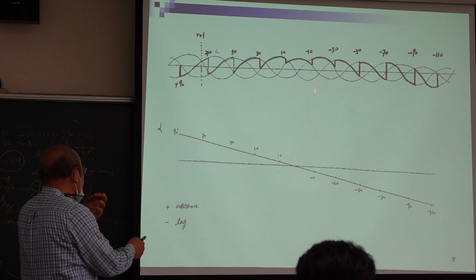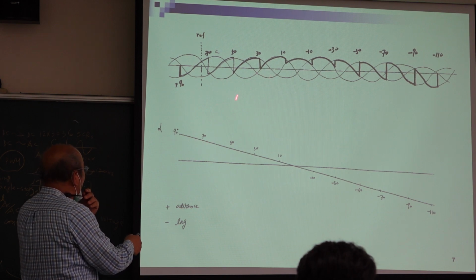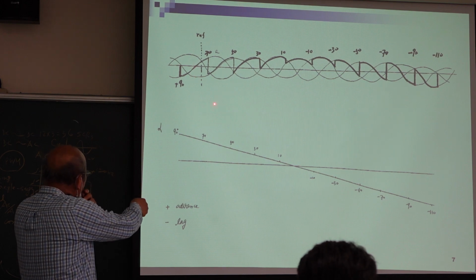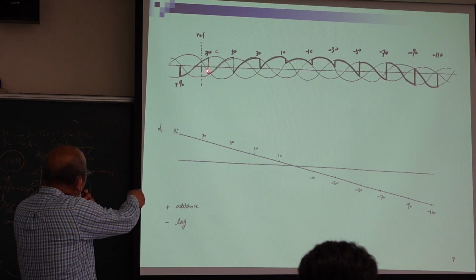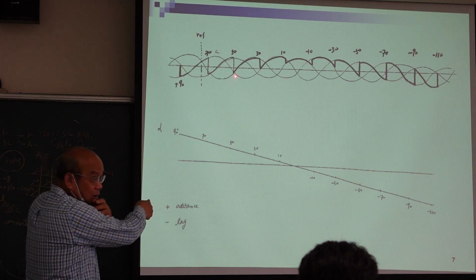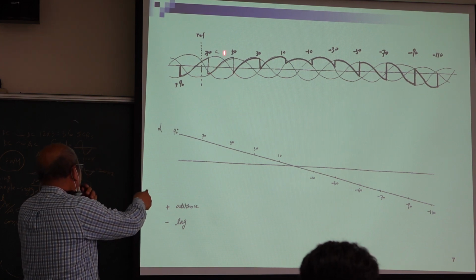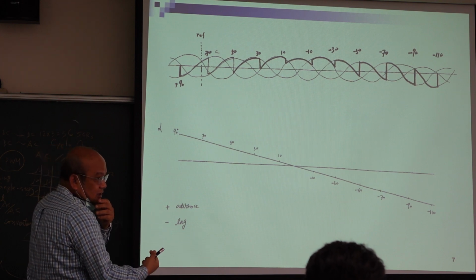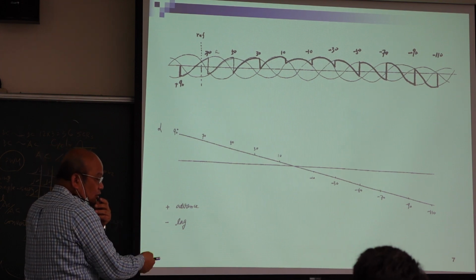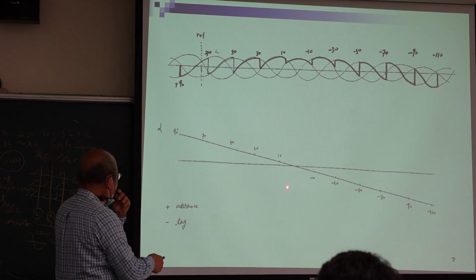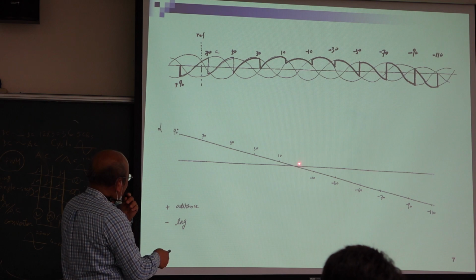Can you increase the frequency for more than 60 Hertz? But for one conversion, you only have one opportunity to control the delay angle, right? So you have no opportunity to go larger than 60 Hertz. You can only reduce your frequency, but you cannot increase it. So this is one disadvantage.